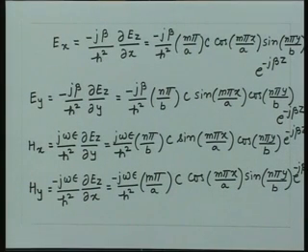So, now we got the complete fields for the transverse magnetic modes, with the understanding that the lowest order mode which is going to propagate on the structure will be the TM11 mode. Now, a few things can be seen from here. The Ez component, for which we obtained a solution, is essentially 0 at these 4 walls.